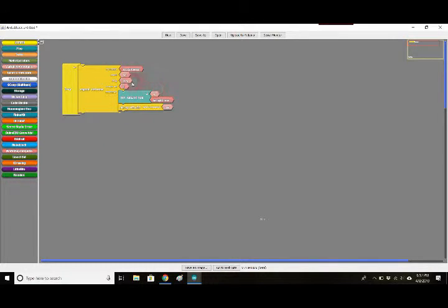In addition to that, we have our start and stop points. So we're starting at 20, and then in steps of 1, we're going 21, 22, 23, all the way to 255. 255 is the maximum brightness, so you can't really pick any numbers beyond that. You are welcome to try if you'd like to. It's not going to break your LEDs or anything. It's just that the Arduino will not recognize numbers above 255. So if you pick 300, it's still going to shine the same brightness as it would if you pick 255.